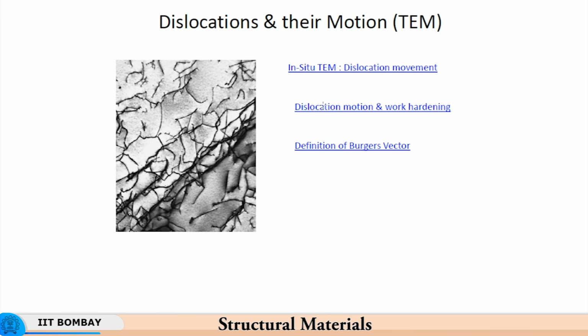That is because the dislocation line and the Burgers vector uniquely determine a single plane. So once one dislocation is formed on a plane, it is constrained to move along that plane. Now imagine a number of edge dislocations multiplying and dislocation density increasing on that particular plane after a certain strain.